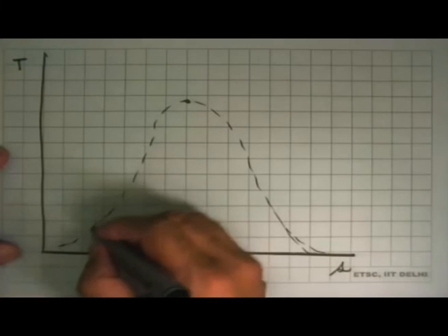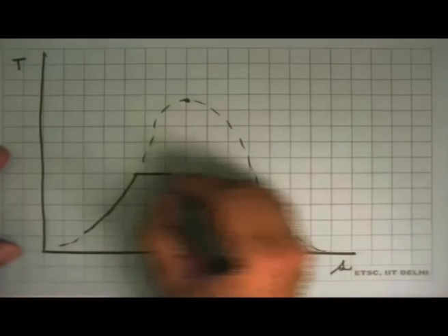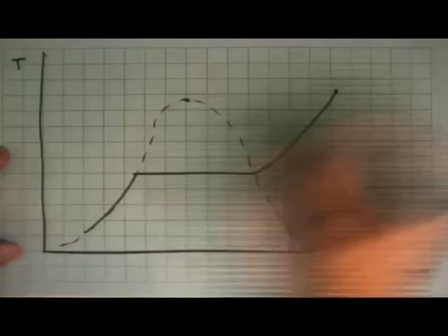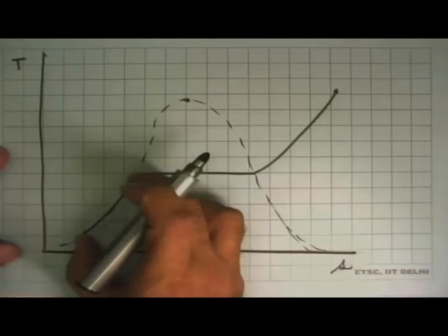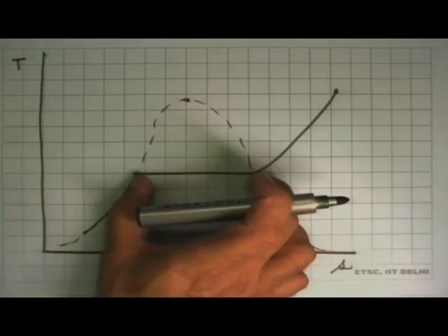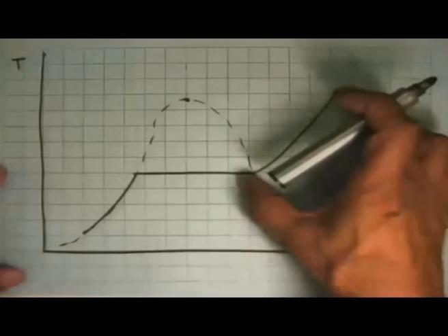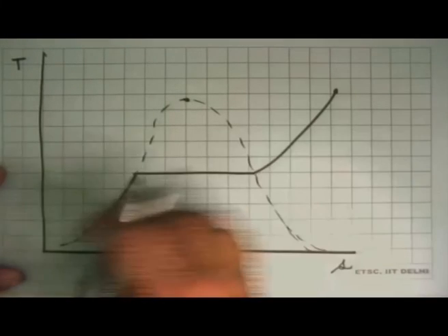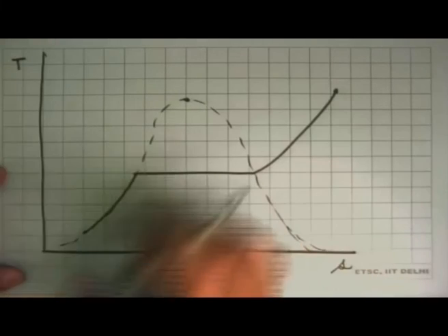If we design something to generate superheated steam, we have to design something that will heat the liquid part. Then we design something that will do the evaporation, where there is a big phase change taking place. Phase change means a big volume change. And then superheating part. So the design of the boiler becomes a 3-part design.